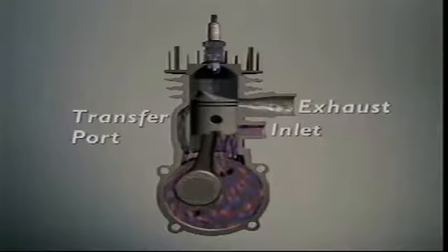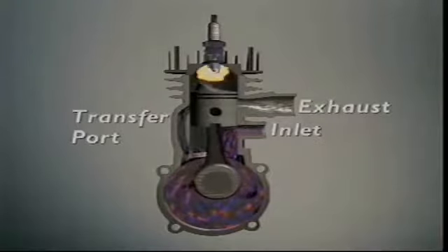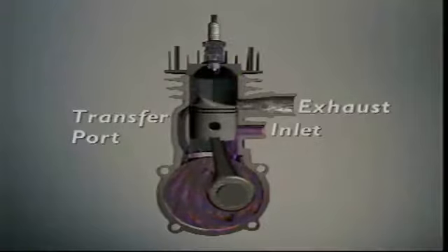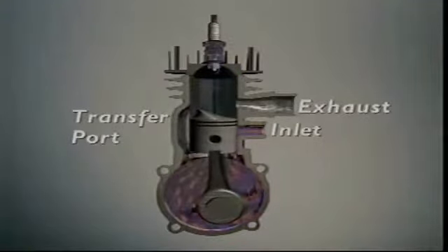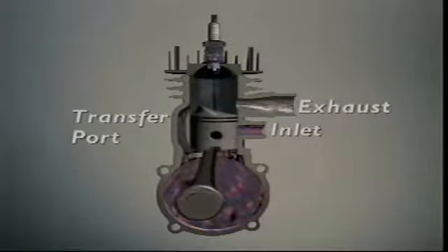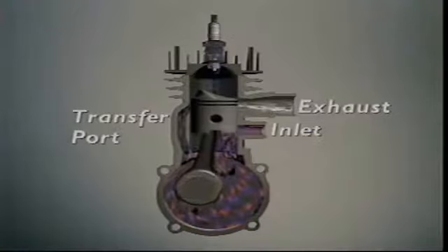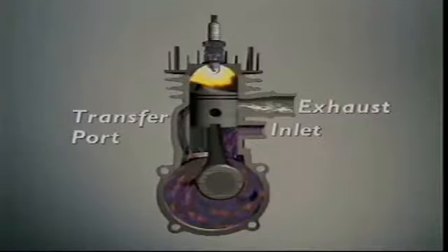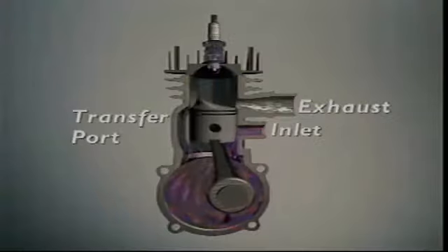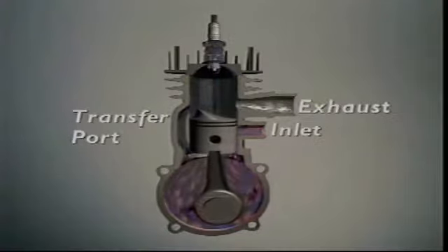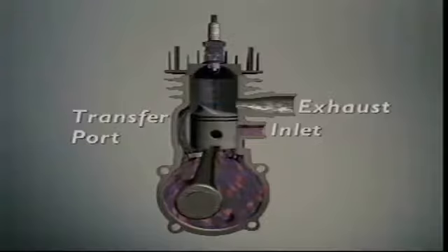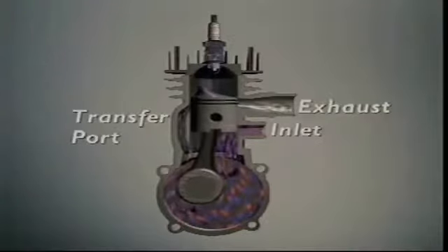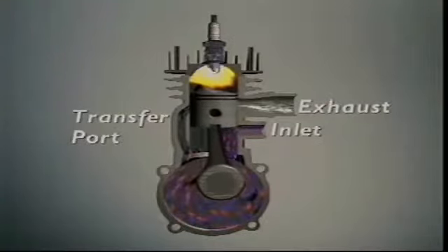As in all internal combustion engines, these 5 events must occur, but not always in the same way. The whole process is a cycle. A new mixture enters and is ignited. Combustion occurs. Expanding gases drive the piston down and turn the crankshaft, which pushes the piston back up the cylinder.